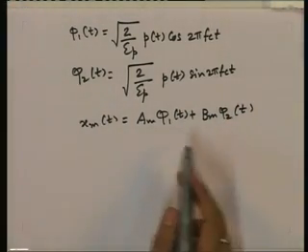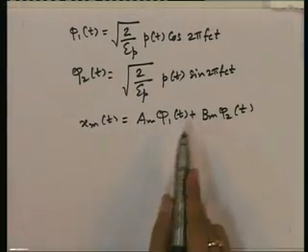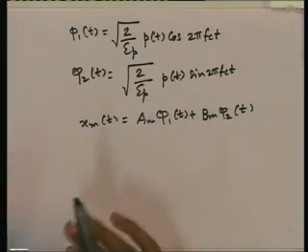Remember that for PSK signal sets, A_m and B_m had some relation, A_m was cos 2 pi by capital M times small m, and B_m was sin 2 pi by capital M times small m, whereas here they need not have any relation. We can choose the points and then say that that is our QAM modulation.